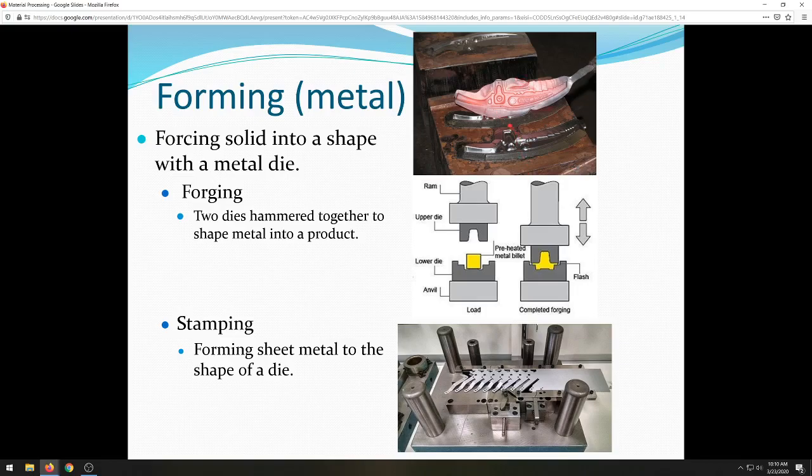And in some cases, it's progressive. If you look at this mold really closely, there's actually two slots in it. The first slot underneath of the part here is most likely less detailed than the second slot. That's like a preform, and sometimes you can run into dies or molds that have 10 steps in them, where you take a chunk of steel or other type of metal, and it just progressively shapes the metal as it goes, and that's kind of what this stamping die is doing down here.